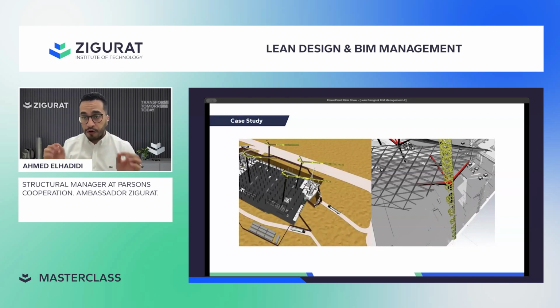But if he thinks from a lean design approach, he thinks, I will maximize the value right now. I want to do the foundation. To do the foundation, I need to put also the tower crane. So this is my milestone. I think about it, dragging this back as a pull phase planning approach. To determine the location of this tower crane, I need the column locations of the architecture. This is the only thing I need.